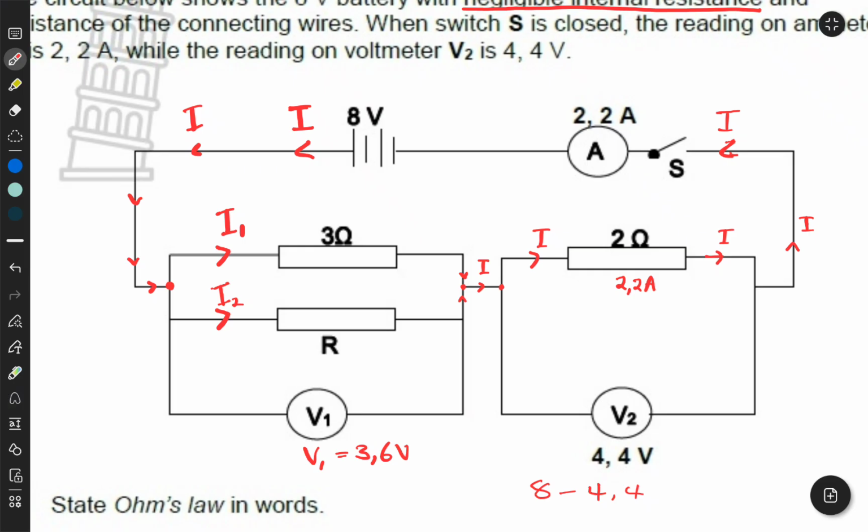Because in a parallel circuit, if you remember, you always get the voltage being the same across the resistors. So even if we had about 4 or 5 resistors and so on, the potential difference will be the same for the entire parallel combination. So each resistor will receive 3.6 volts. So the only thing that divides is the current. So always remember those simple rules, okay?